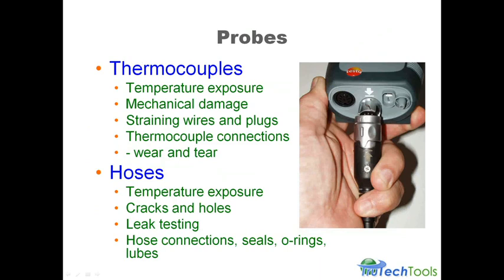If you're an HVAC contractor, you have access to nitrogen. We test them; we bring them in the shop. We take a vinyl tube, a half inch in diameter, that a probe can slide into but the nitrogen can flow around. We'll slide it onto the bottom of a nitrogen regulator, just crack it so we get a trickle of nitrogen out, like you'd use for brazing copper tubing. Put the analyzer in there, and because it's pure nitrogen, the O2 should go down to 0, right?